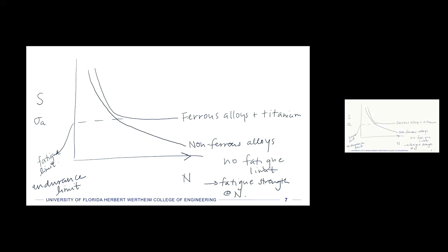An example of a non-ferrous alloy would be aluminum, bronze, brass, a lot of things made of copper, okay? So they have no iron. That's what non-ferrous means. This will come into play later when we start looking at effects on some of these curves. We really have to take care whether we're talking about non-ferrous alloys or ferrous alloys.